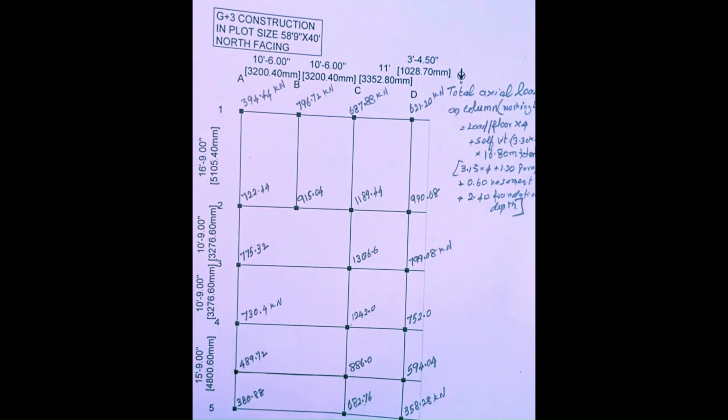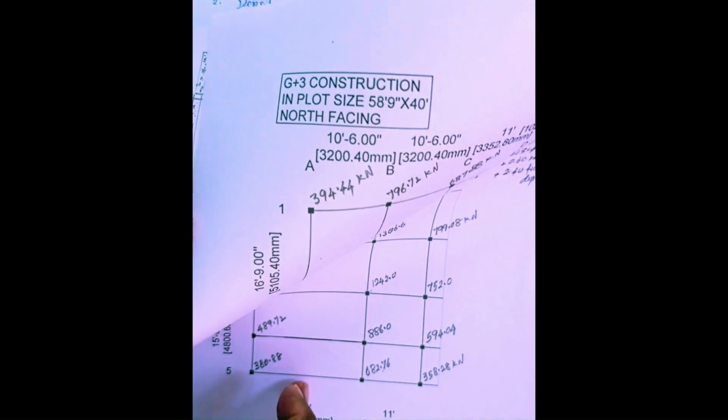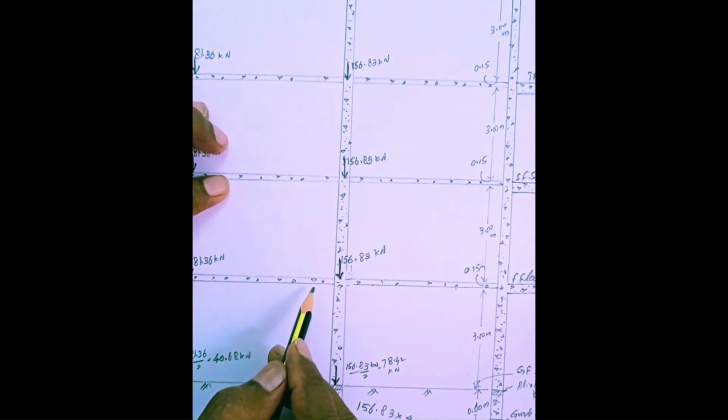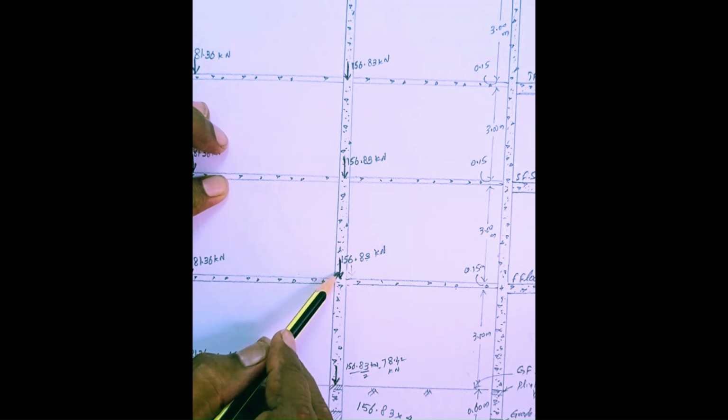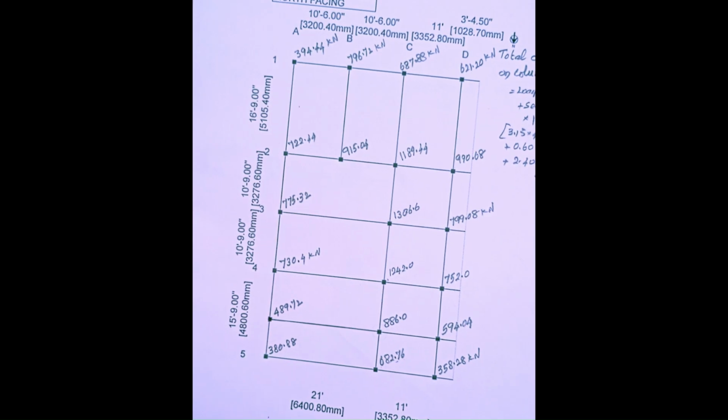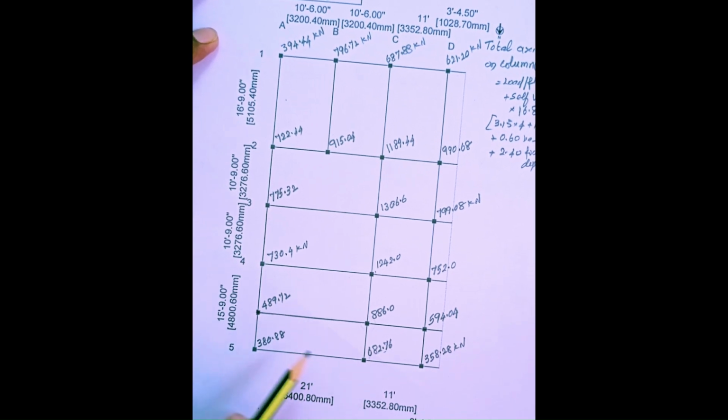You see in this drawing also, if you take this, the beam goes from here, so this moment equalizes this moment, and so the axial load of these is enough to decide this footing or this column. So finding the eccentricity or the bending moment in the column we shall take in some other next tutorial.